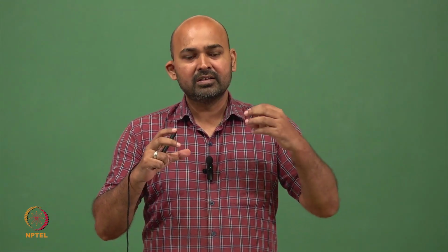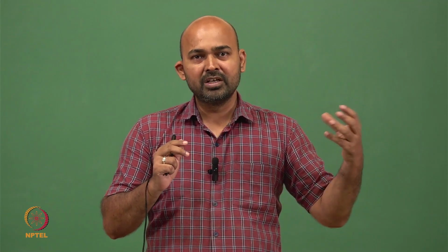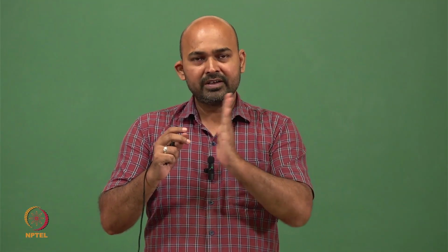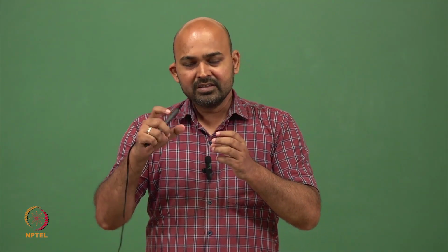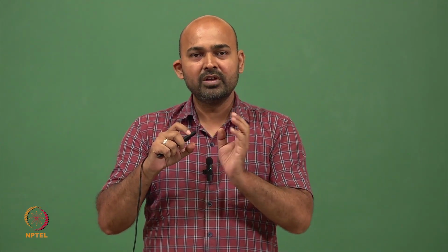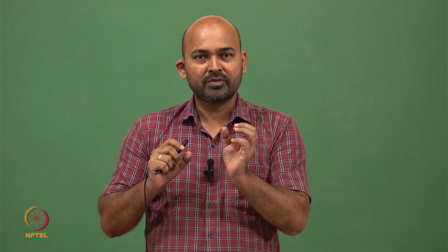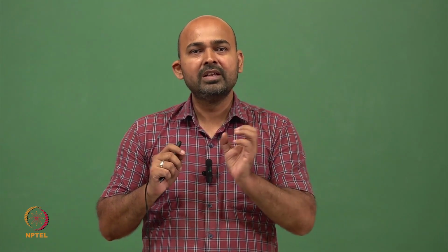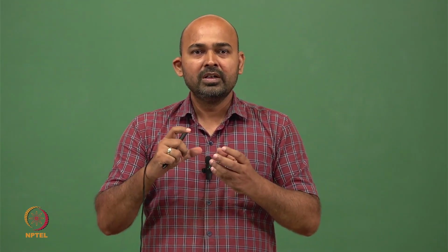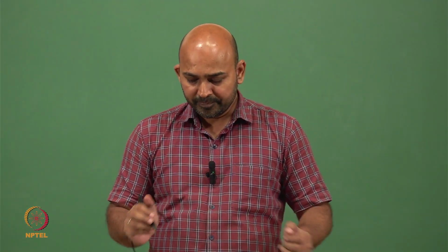When a wave hits, this diaphragm moves or shakes depending upon what kind of wave it is. So this diaphragm responds to the wave and it moves, and there is a transducer attached to it which measures how much the diaphragm has moved, and based on that we can calculate the amplitude and the frequency of the incoming acoustic wave. So this is how an acoustic wave is detected by a microphone or hydrophone.